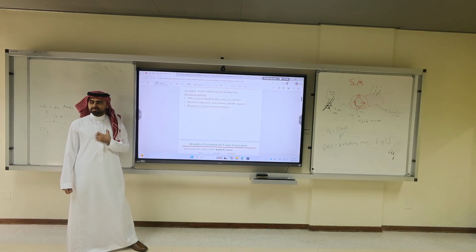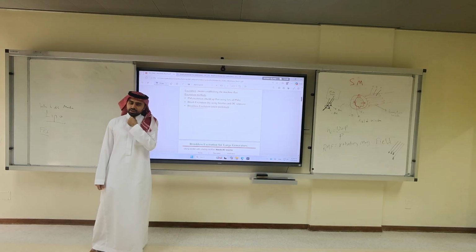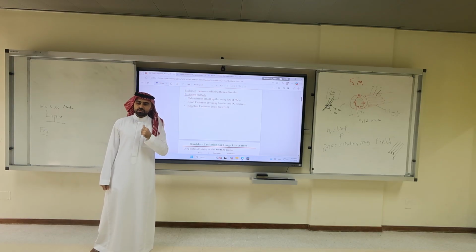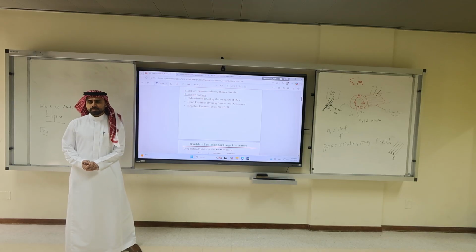Explain it again? Quickly? Okay. For the brushless excitation, we can also use a DC source, correct? I don't think so. For brushless excitation, you have to always begin with AC or permanent magnet, because we rectify it immediately, so why does it need to be AC? You can do it, but I don't think it's a common practice.